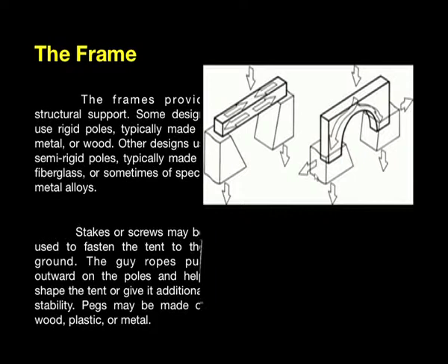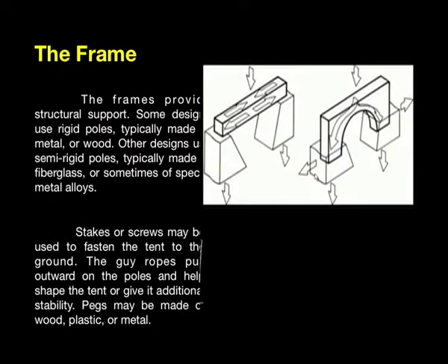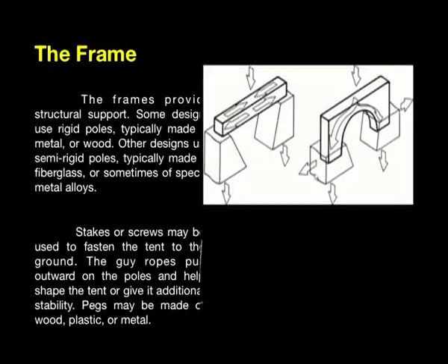When the lateral forces are more than what the arch can carry, there is a horizontal splay which the arch creates, which means the supporting members go outward, and the arch caves in on its own. The arch is otherwise a self-supporting structure, which in this case it is not. The weight of the arch itself and the weight acting on top of it makes the arch splay outward and the thrust defeats the arch's purpose.